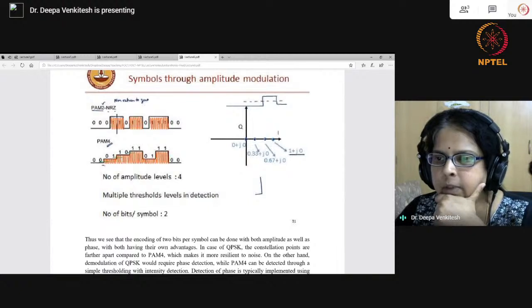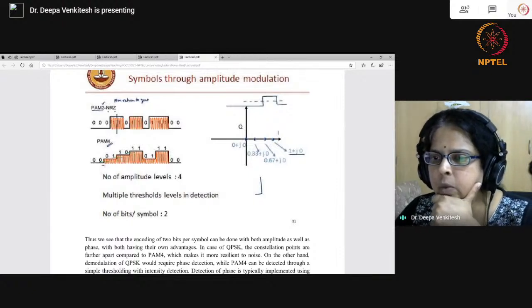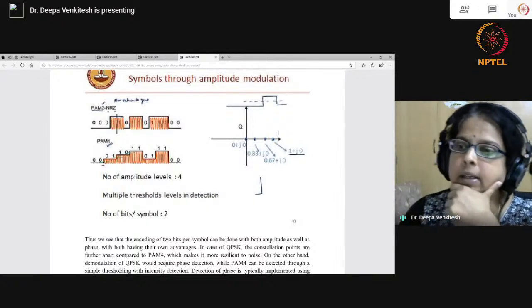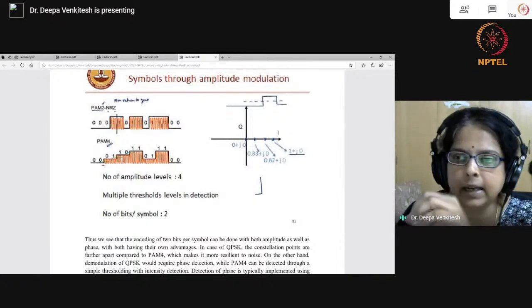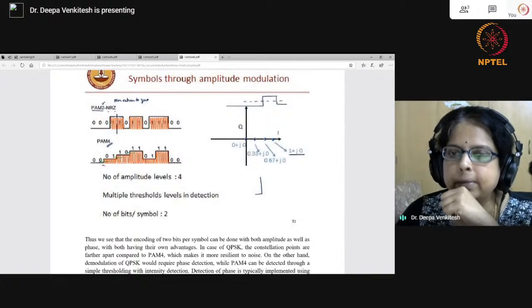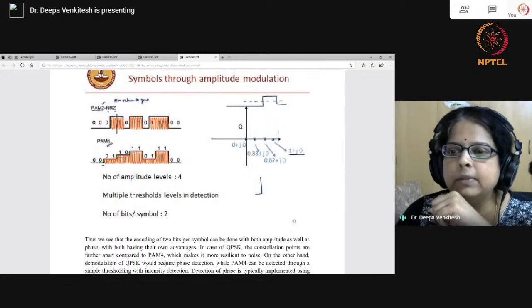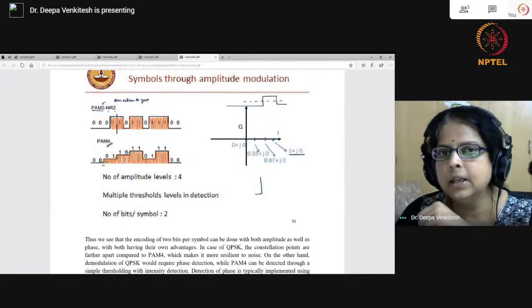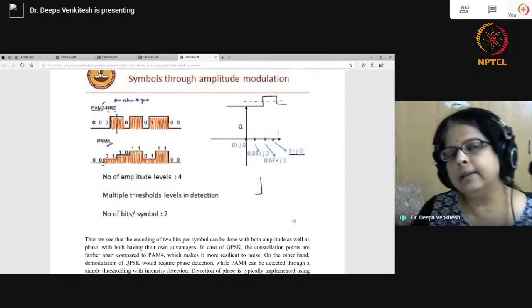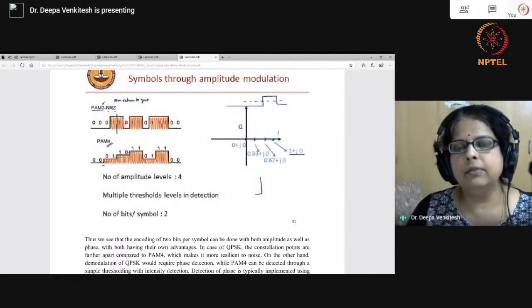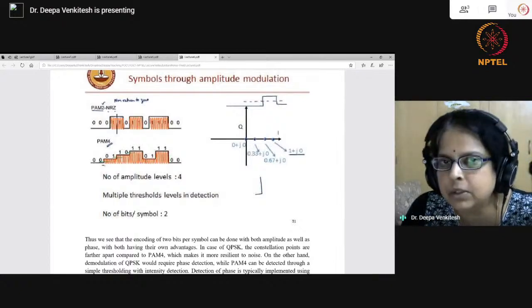It's a question from Vishwanathan. Why do we see a fuse in a fiber? Can we reuse the fiber with a fuse? So fiber fuse happens when the entire fiber melts. This typically happens not in the fiber used in communication systems. A fiber fuse happens in fiber laser systems which use very high powers, of the order of kilowatts